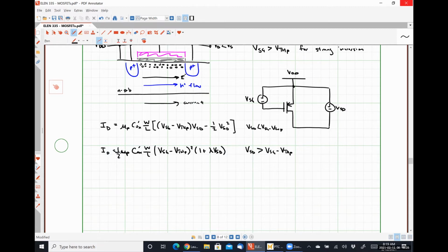It doesn't have currents flowing in weird directions that are counterintuitive. It doesn't have extra negative signs and all that kind of jibber jabber to screw things up. All the voltages here are positive, including VTHP. To me, this is a much, much easier way to look at a Pmos transistor and actually understand what the heck is actually happening here. And these two models that we've brought in here actually can illustrate something pretty interesting as well. Before we get into our biasing circuit, this is technically the subsection after the biasing circuits.